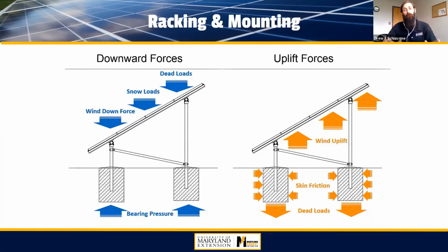What I will say in terms of the structural, before we move into more electrical aspects, you have to account for the strength of the system. And we're going to spend most of our time here on out talking about ground mounted, but similar applications apply to rooftop systems. But I'll say when you design a mechanical support system for the PV, it has to be strong enough to hold the system up, not only from the dead loads, that would be the weight of the actual system. You want to make sure it holds that up, of course, but you also have to account for the snow loads and wind forces as well.